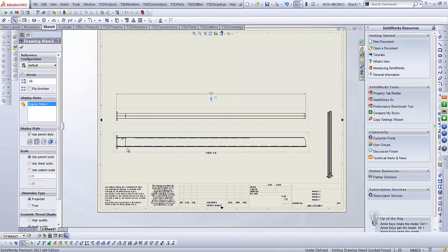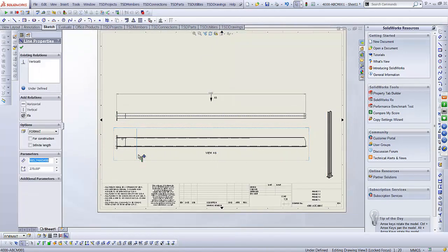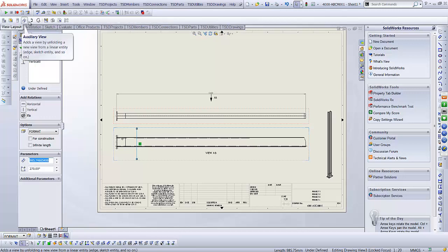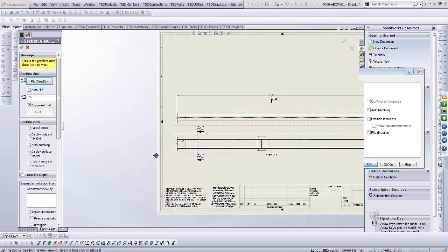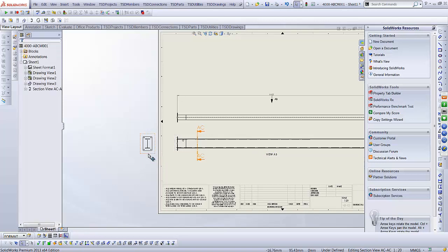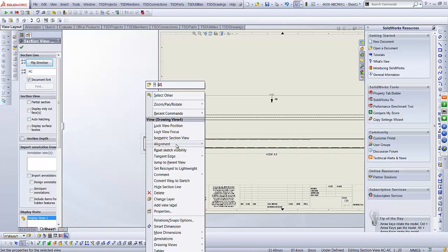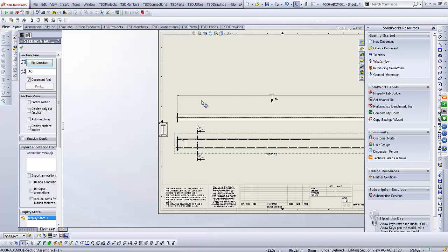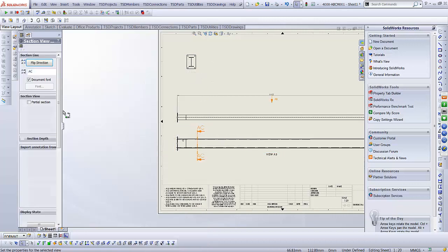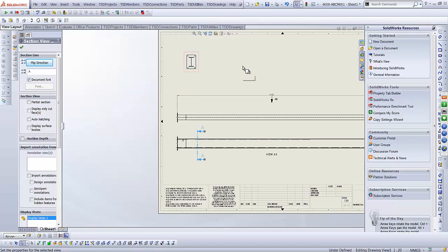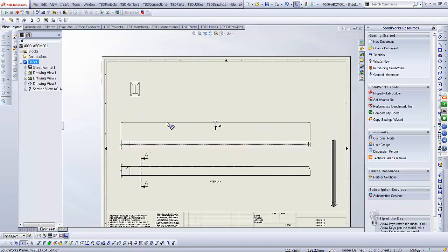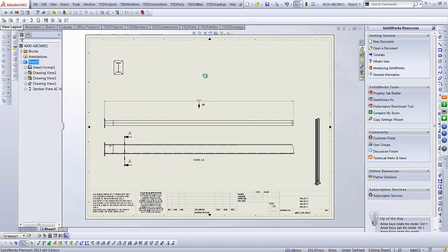So I just want to put a sketch in here for a section view. Just go up into my sections. Okay, detach the section because at the moment if I move it, it slides along. So I just want to right mouse click, alignment, break alignment, put my section up there. Section A, give it a label that actually means something. I can run dimensions all over that.